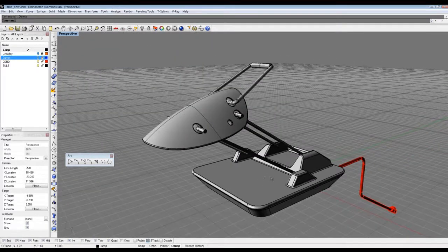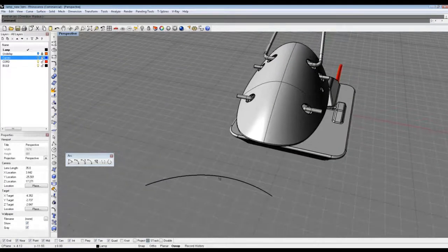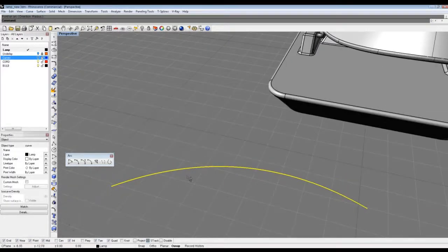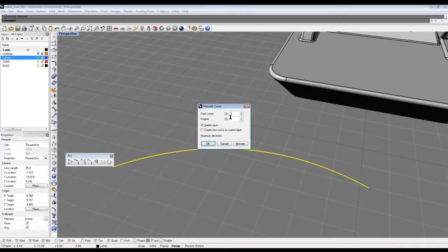Okay, let's look at Denise. Denise wants to know, how can I add a control point to a curve? Oh, great question. I probably went way too quick over that. There's a few ways you can do it. I'll just show you two. So you have a curve here. The first thing you can do is rebuild the curve, and that'll add an even array. So we'll use 10. Right now this curve, you can tell by the point count, has 3. Whatever that number is, that's what it has. And we'll make it 10.